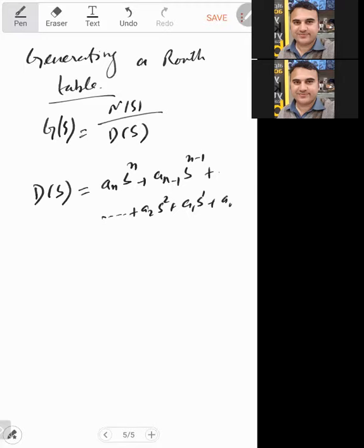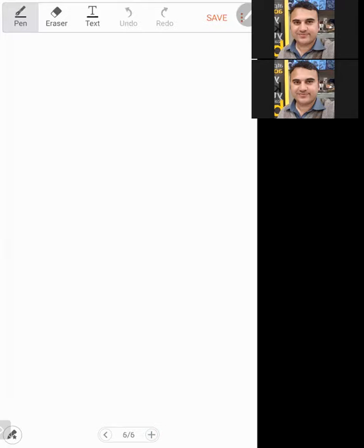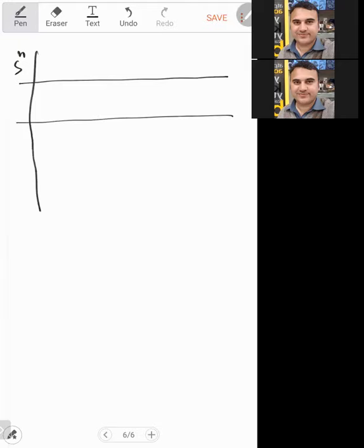And let's say we have this equation. The coefficients can be plus or minus also. It's not necessary that they are all positive. So we got this equation, and now we will form the Routh table from this equation. So what is the highest order? The highest order is s^n. So we will start with s^n.